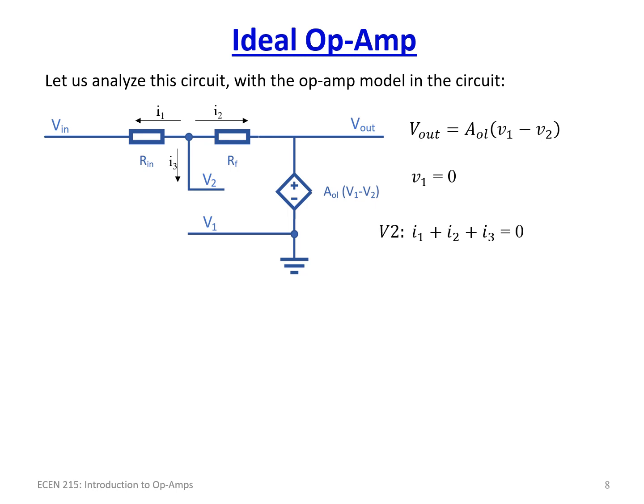Now, what can you tell me about I3? I3 is staring into an infinite resistor. There's no place for this current to go here. It is staring into infinity. It's just infinite resistance. So there is no current flowing in I3. So we can simplify this by simply going, that's gone, because I3 is ideally 0. So we can reduce this equation simply to I1 plus I2 is equal to 0.